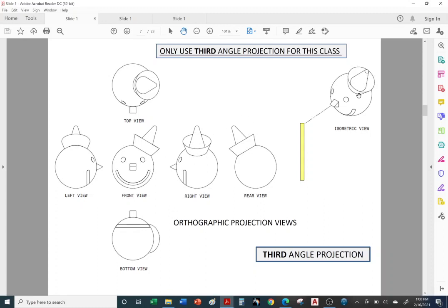Okay, if you want the right side view, you would tell your buddy, your friend, to hit Jack and have Jack rotate clockwise. So if Jack rotates 90 degrees around the pole and you're standing out here, you're going to see the right side view. If Jack is hit counterclockwise after 90 degrees, you're going to get the left side view. Okay, if you want the top view, you just tell your buddy to hit Jack straight up. So Jack would rotate 90 degrees upward, go vertical, and you would get the top view, and so on.